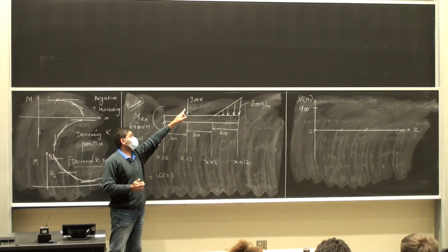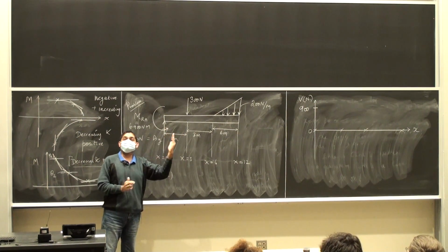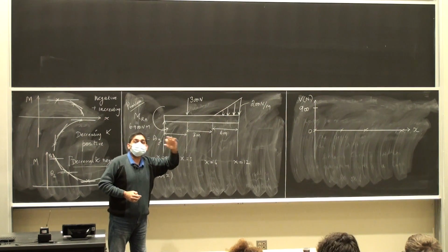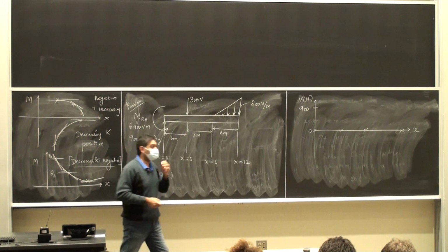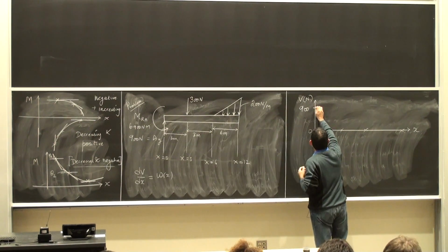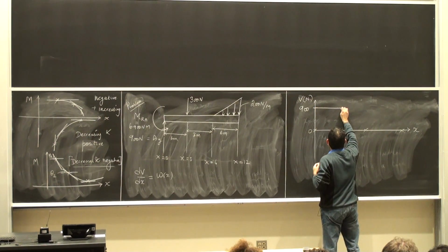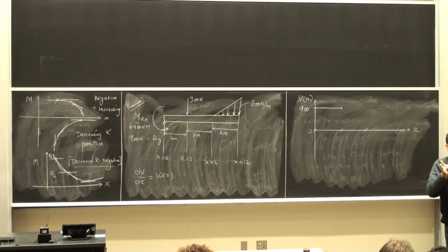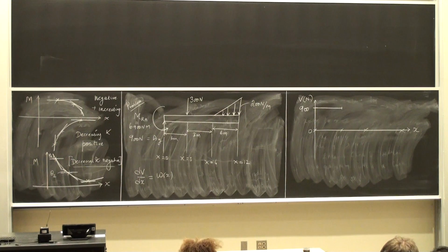Right before I hit this force of 300 newtons, there is no distributed load, which means that I have to travel as a straight horizontal line of 0 slope. Okay? Am I making sense here? No calculations whatsoever. What's my next step?